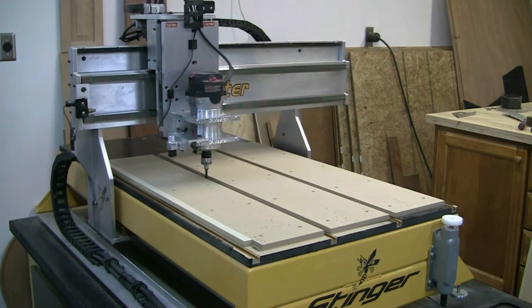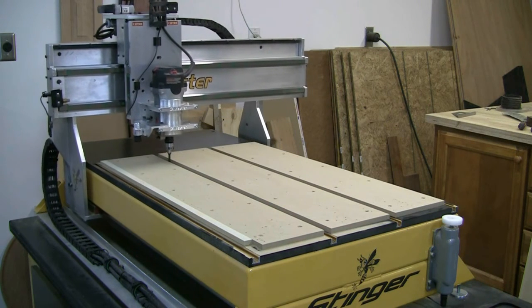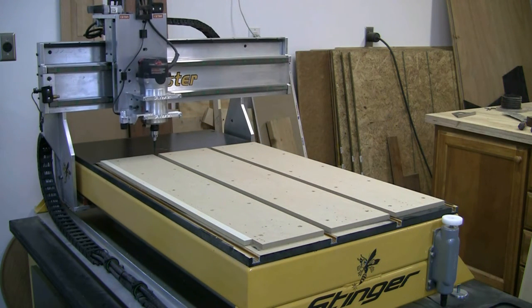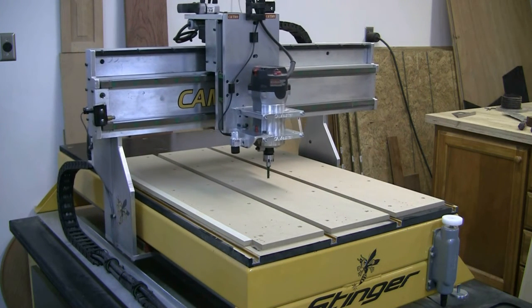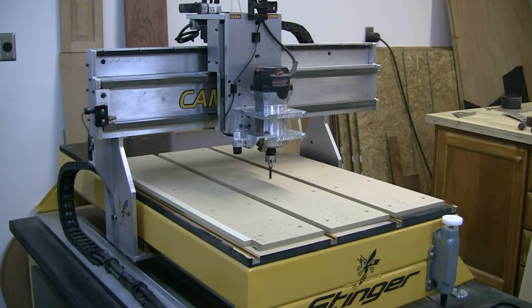These feeds and speeds are high, well the feed is, not the speed. The feed rate is high. Pause it again for a second. So the only thing you've got to be really careful of is, now I'm doing a jog across to the next cut. So you have to make sure that your safe Z's are high enough. You don't want it to come up 0.1 of an inch if I'm 0.4 in the material, otherwise you're going to hit the side of your grooves.